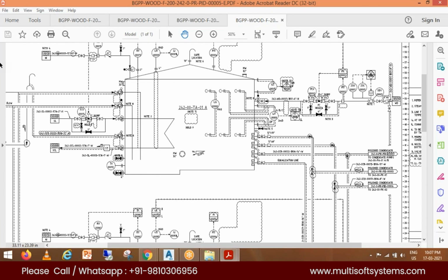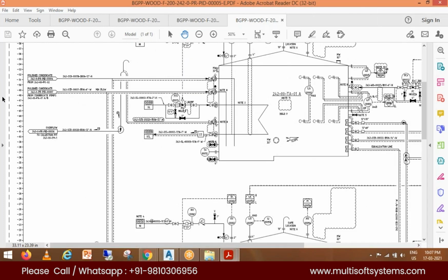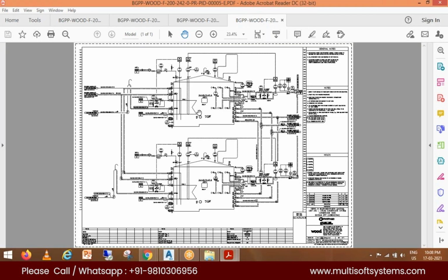In PNIDs, it is a semantic difference, basically. So in PNIDs, when you see, it is a small unit part of your plant. It is a very small portion of your plant. If we see the overall plant, this PNID contains only two tanks, and with this kind of pipelines, pipe runs available. So that's why for PNIDs we are using this pipe run term.